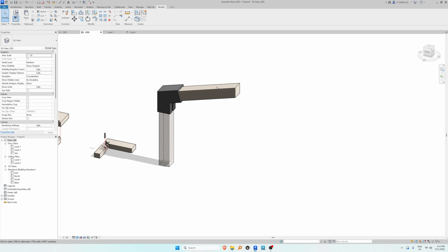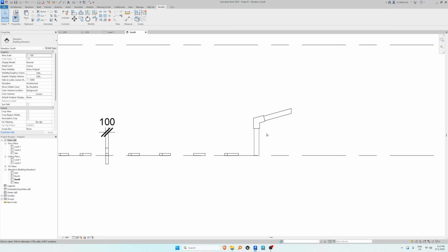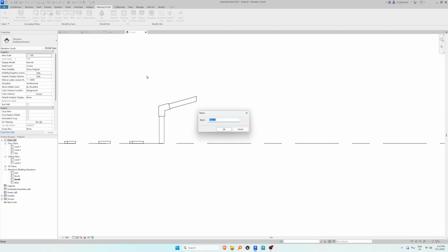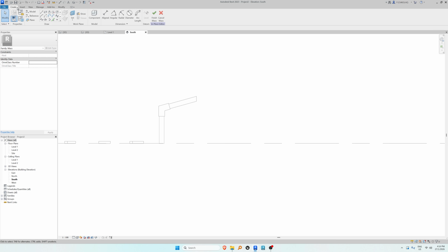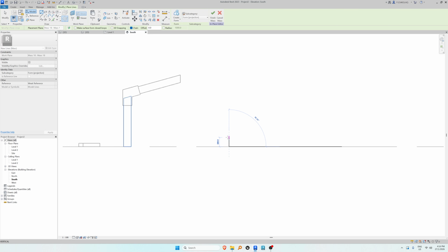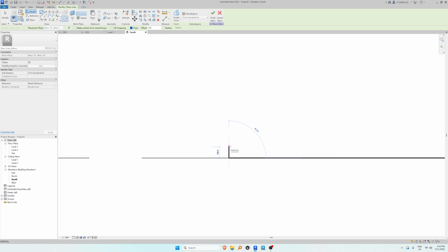perhaps using the normal tools, right? This is just something a bit different. So another complex joint that we can make is just go to the south elevation, massing and site, in place mass, right? So you have this. Let's make pick a plane, right? Just leave it at pick a plane. Just pick the old one, it's fine. Let's make this at 100, maybe 100.